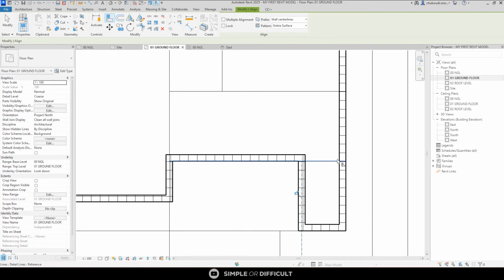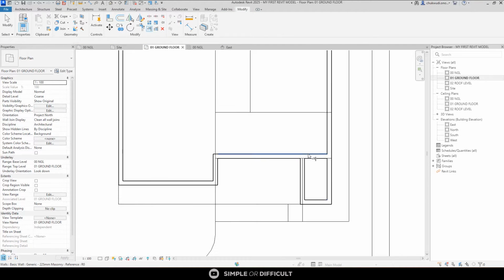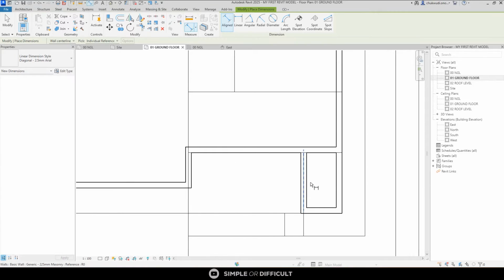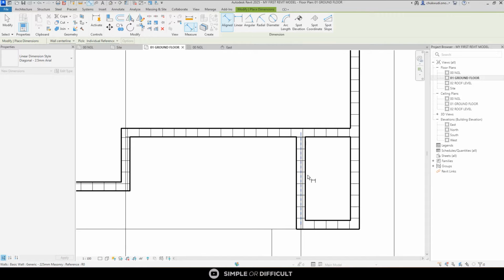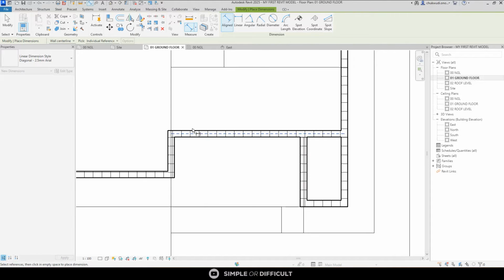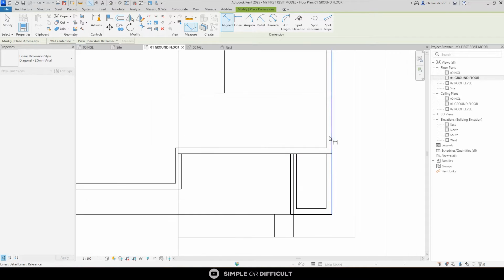All right. I want this wall to terminate over here. So I'm going to use this to select this, select that. It is going to terminate that. Let's see the amount of space we have now. Now, when I select this dimension, you find out that it's snapping to the center line of this wall. Now, I want it to snap on the face. Okay, for it to snap on the face, I'm going to come over here and set it to wall face.